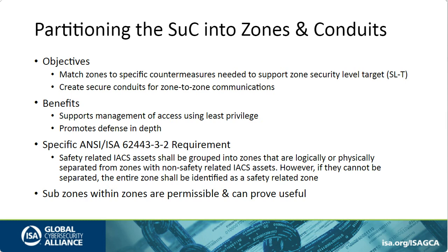The number of people and the type of people who need access to the field equipment is most likely different than the people that you would allow access to the engineering workstation. So even though they're all part of the safety zone, creating subzones that allow some differences in the countermeasures and how you implement those countermeasures can be very useful.